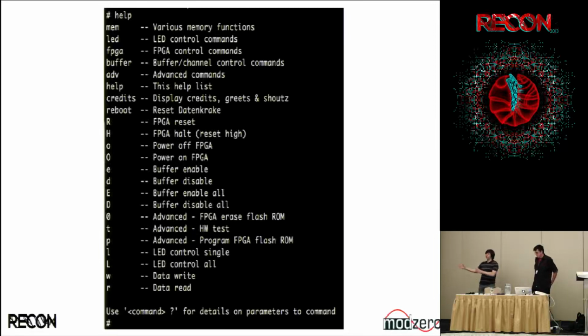What we did for you is if you implement something on the FPGA, you can write directly with this write command. You say address, data, and 1 second later, all of a sudden, your hardware either starts working or it doesn't, depending on if you did a good job writing the logic or not. But this is a very important feature if you're doing FPGA designs, because it's really annoying to figure out a way how to test if your synthesized design is actually performing as it should.